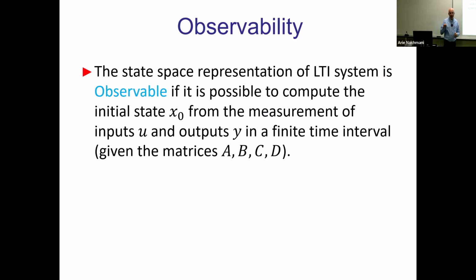But the controllers that we will be building connect to the states, which means we will take the state, multiply it by all kinds of numbers, and return it back as a feedback loop. This will be our state controller. Which means that to design a state space controller, you need access to all of the states. So you need to measure all of them somehow. And sometimes you just can't. It's a problem for the natural design of controllers. If you cannot measure something, you cannot connect a wire to it, so you cannot return the feedback loop. You don't have access to it.